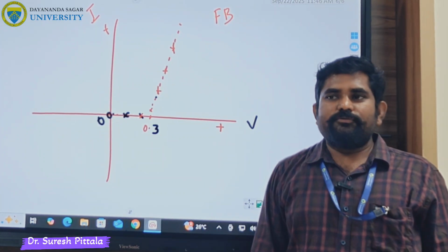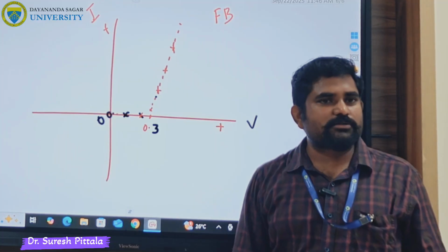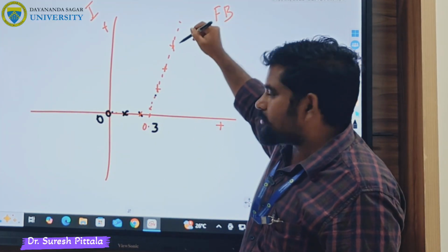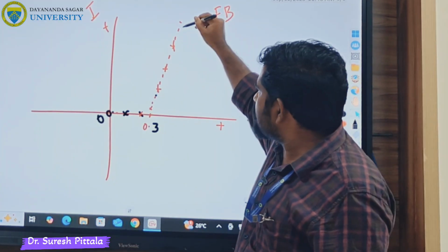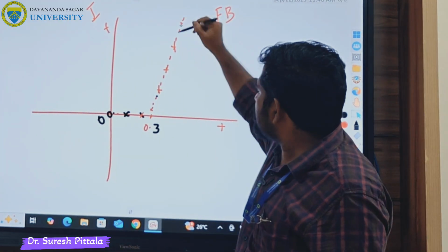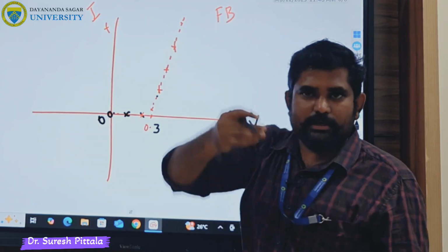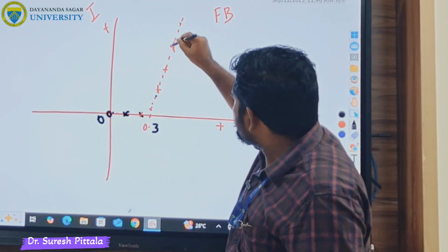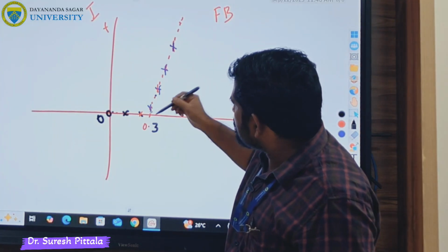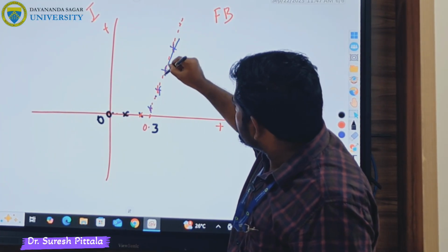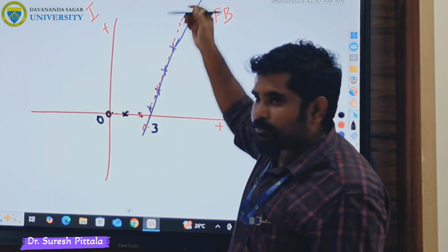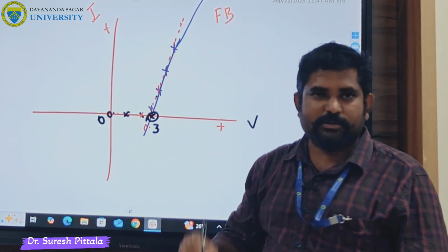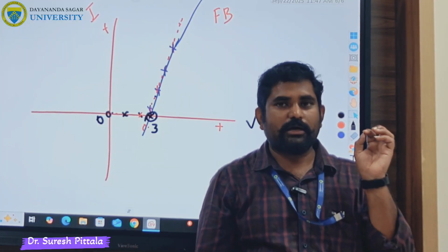Now, in the aim you did not say, we also want to find out what the knee voltage is. Knee voltage is something like the operating voltage. To find it out, you take a straight line and extrapolate it to the origin. We don't have points everywhere, only these many points. So I draw a line connecting all these points. We say it is extrapolation, right? Extrapolate to the x-axis; wherever it touches the x-axis after extrapolation, that is called knee voltage or threshold voltage in the forward bias.